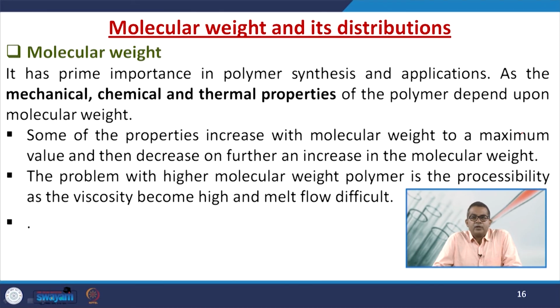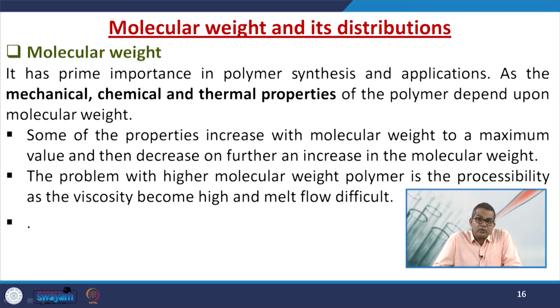So, when we talk about the mechanical, chemical and thermal properties of a polymer, they usually depend upon the molecular weight. Now, some of the properties may change with the molecular weight, and sometimes they may increase to a maximum value, and sometimes they may decrease on further increase in the molecular weight. So, it is a very sensitive type of thing.